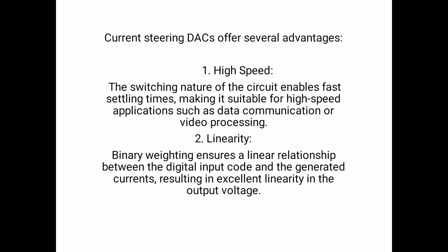Current steering digital to analog converters offer several advantages. First one, high speed. The switching nature of the circuit enables fast settling times, making it suitable for high speed applications such as data communications or video processing. Second one, linearity. Binary weighting ensures a linear relationship between the digital input code and the generated currents, resulting in excellent linearity in the output voltage.